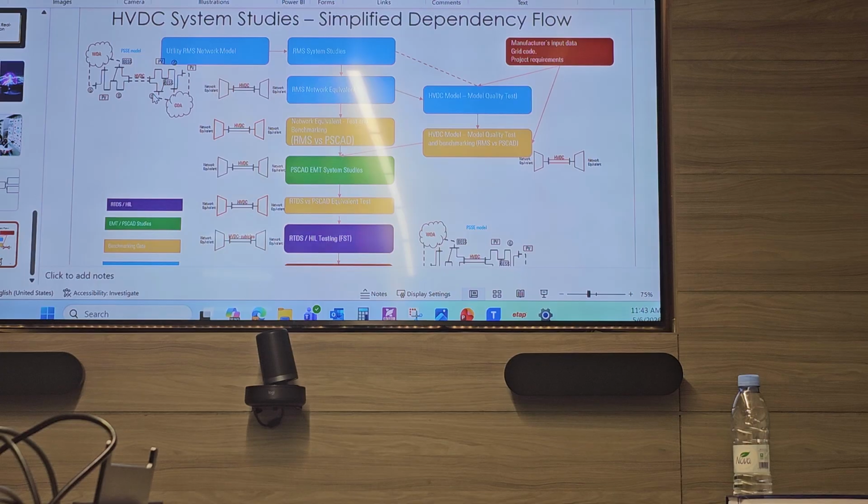So even the benchmarking will be done using multiple scenarios, not only one scenario. The scenarios are defined somewhere in the beginning during these studies. They say, okay, these scenarios are most critical for our network. So you use extreme cases, maximum and minimum, to model, and you simulate faults in these. You expect that when a fault happens somewhere in between, the system will behave well, if it behaves well in these extreme cases.